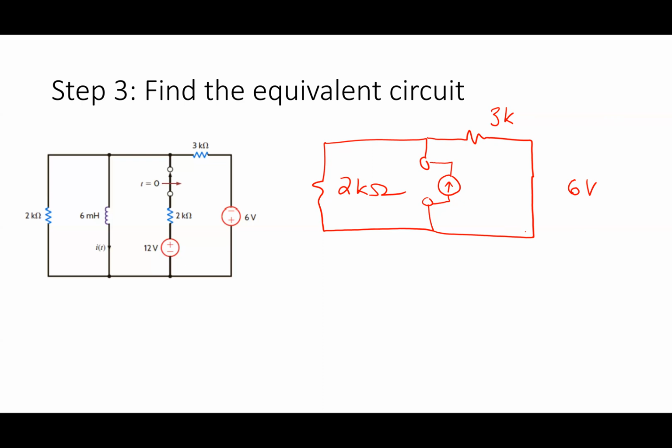So the R Thevenin is basically the equivalent resistance that current's going to flow through, which in this case is 3K in parallel with 2K. The way to think of it is, how is that current going to flow into that circuit? Early in the semester, I see a lot of people say, well, it's 3 in series with 2.